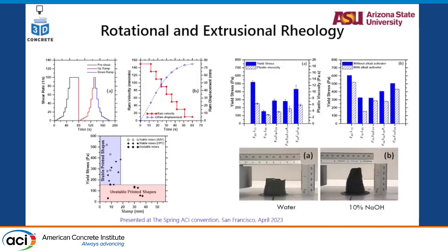Right, so the classical rotational rheology that we all have become fans of, but we figured out that it's all nice to talk about yield stress and plastic viscosities in a rotational rheometer that you test, but to translate it into actual mix and see how that translates. Once you do enough number of tests, you can get some fits, but does that really relate to actual material performance? Big question. So we have used quite a bit of extrusional rheology, which I'll show you what that is.